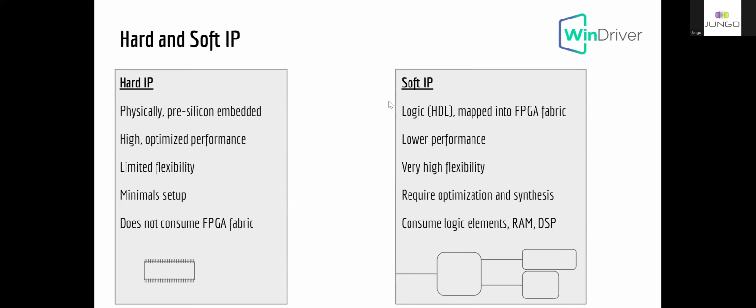Soft IPs, on the other hand, are logic. It is mapped into the FPGA fabric. You can add it and you can remove it. The performance is lower than the hard IP, but it is highly flexible, and we will see how you can affect and change the parameters and configurations in a design.